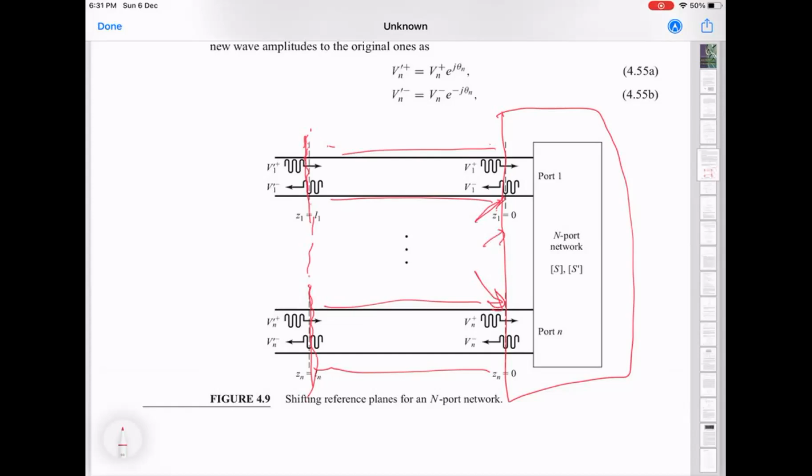So in this example, they just talk about a simple case where this is just a section of an ideal transmission line, 50 ohms matched. Then we know from previous discussions that this does only trivial things, for example a phase accumulation. And Joydeep, going back to this very old question you had asked about the phase accumulation, this is basically that. You're going to get an additional phase, but if you're looking at only magnitudes, you're not going to see any change in the response,